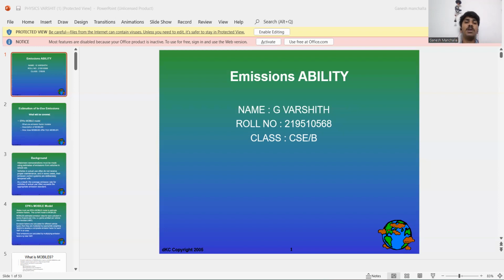Relation of emission control performance: how vehicle emissions increase as a vehicle accumulates miles. The basic emission rate BER is equal to the zero mile level plus deterioration factor times accumulated mileage. The BER is a function of the following: assumed owner maintenance and tampering habits, vehicle age assumptions, mileage assumptions, emission control technology.